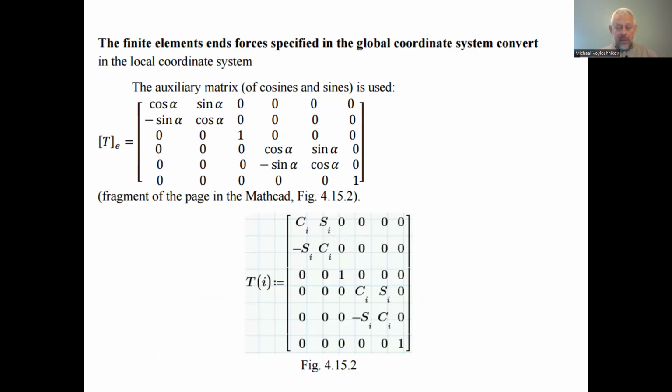But if you consider the total rod with 6 coordinates, 3 coordinates of the beginning, abscissa, ordinata, and the angle of rotation, the angle of the bending of the beginning. And this is like for the forces applied to the beginning and to the end: the bending moment at the beginning, and the forces applied to the end, the horizontal force in the global coordinate system, the vertical force component and the bending moment.